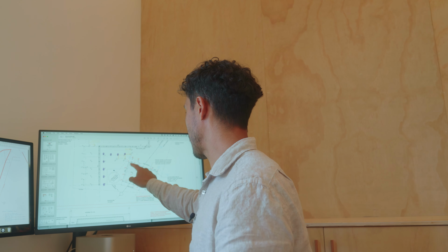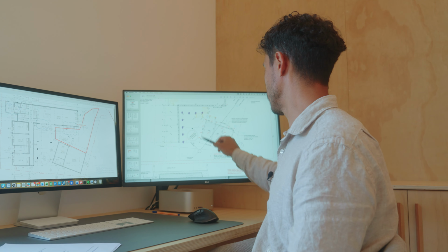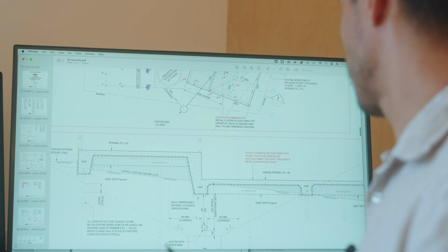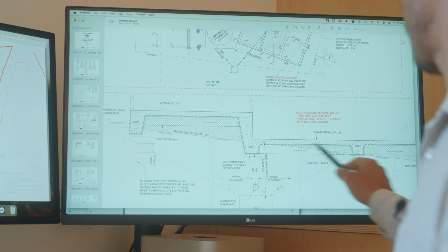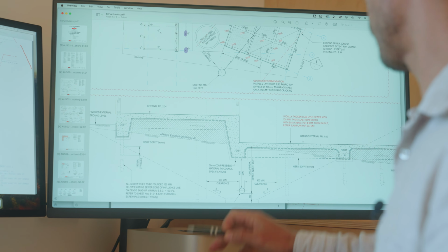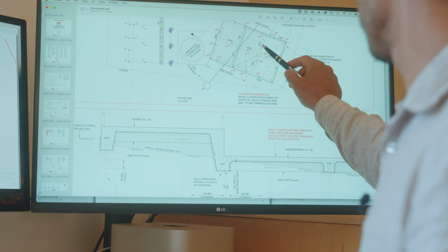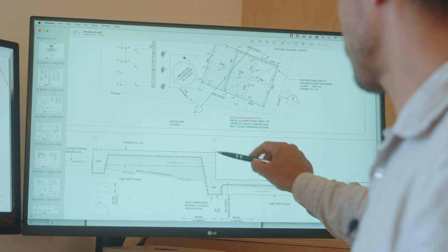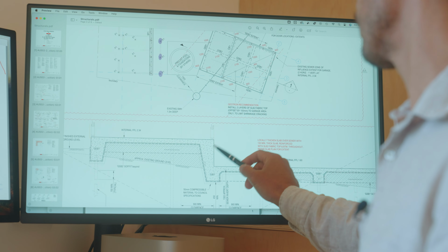And they know how this is designed. For instance, obviously the size is there. Now we can see where the edge beams are, where the internal beams are, and then the section drawings are drawn in of how that looks. Now it's really important for this point here that there's actually a step down there, and to build that step down is actually a significant amount of work. So that's something we really need to know.